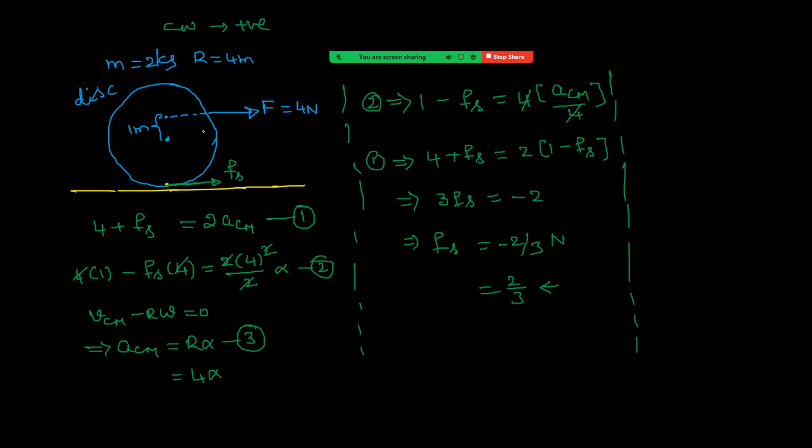Okay, let us take this as a height h, which we have to calculate. So I'm taking this height as h, which is unknown, right? Let us see what happens. We want to calculate the h value for which frictional force should be 0.